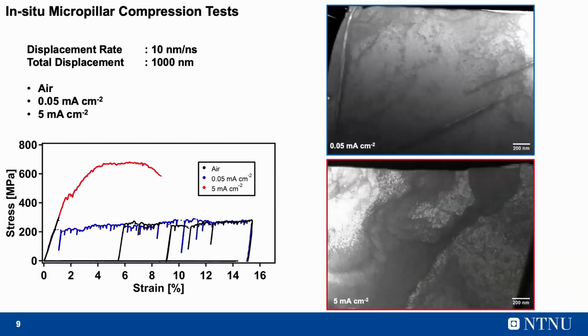To further analyze these hydrogenated cases, we took the STM images as well, as you can see in these two figures. The first one is for the low hydrogen concentration, the solid solution hydrogen concentration, where we can see the slip traces, and there are also dislocations around these slip traces. However, in the hydride case, at the upper side of the micropillar, we can see large, intense strain fields because of the hardening and the higher yield stress and the hardening mechanism as well.